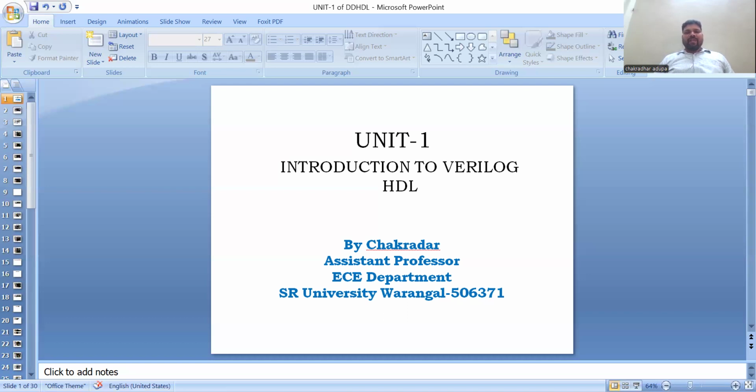What is functional verification in Verilog? For functional verification in Verilog, the process typically involves writing a test bench to simulate the functionality of the module using Verilog design. Here are some of the key steps and examples you can use to verify the function, considering a 2x1 multiplexer.